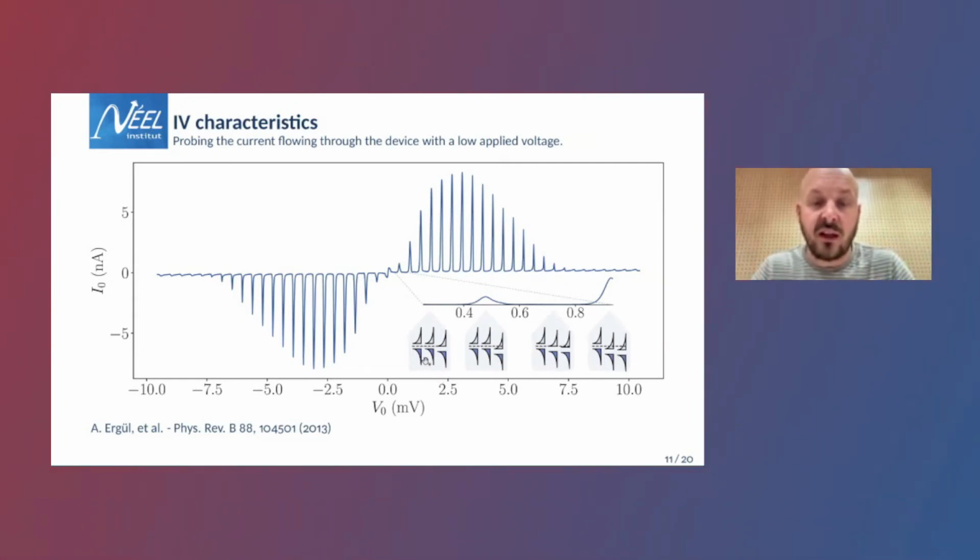So what happens is that whenever you increase the voltage, one junction goes to the subgap state, so the current drops because it's a very high resistance. Then it remains low as long as the holes and electrons become aligned again, so you can flow a current, but then another junction goes to the subgap state, so the current drops again. And you repeat this every time you reach an integer multiple of 2 delta. We are not the first to observe that. This was very nicely discussed in this paper from the group of David Haviland.